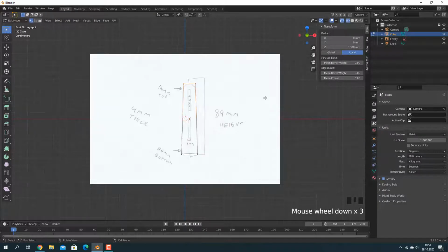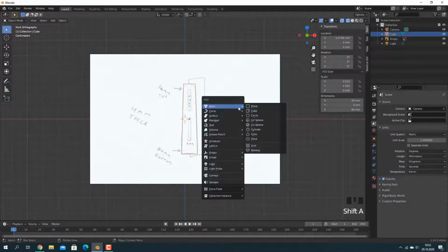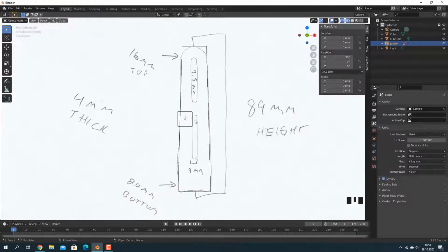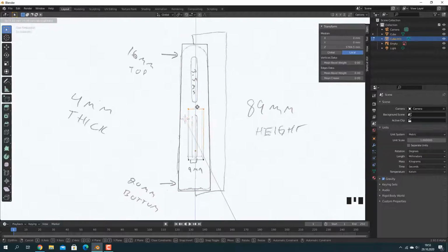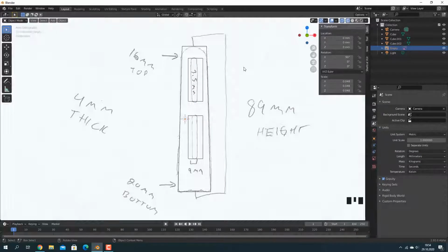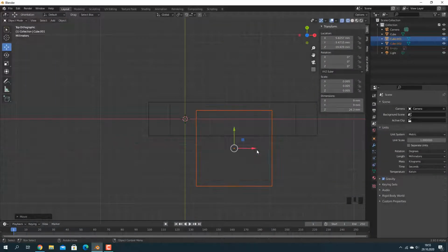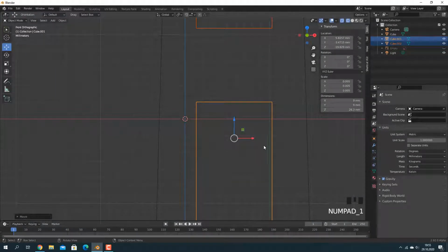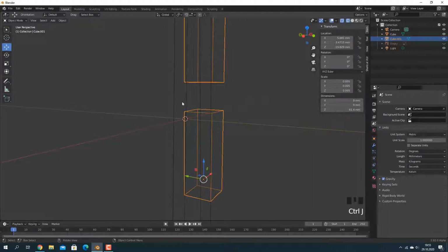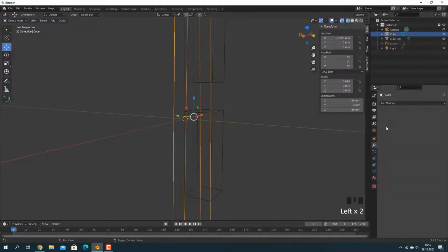We are going to be using Booleans to cut holes in the model and create the parts we need. Create a cutter object box 9 millimeters large in all axes. Sizing one object and copying it to the second opening. Here we are adjusting the placement both on the depth and the placement from the front. We join the two new boxes to make it one cutter object.